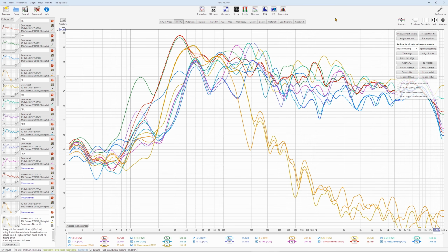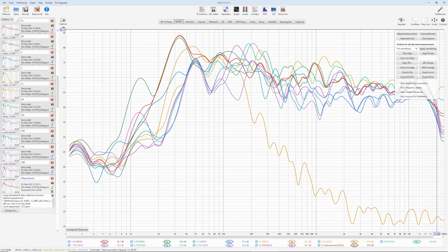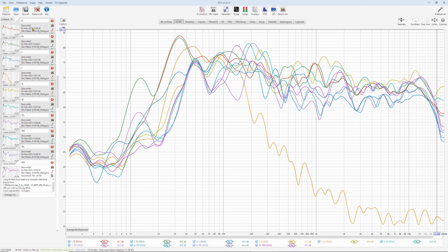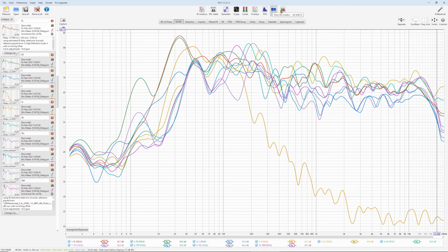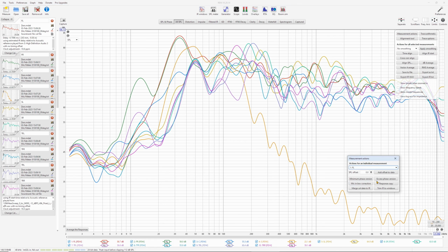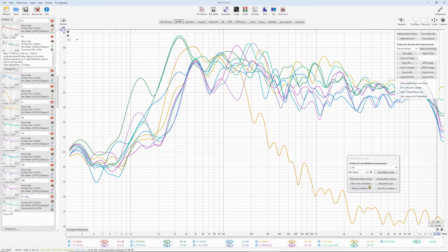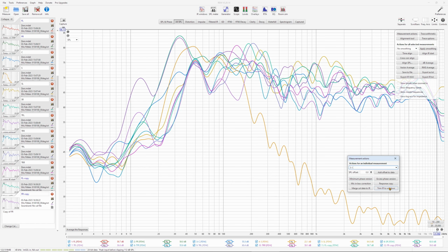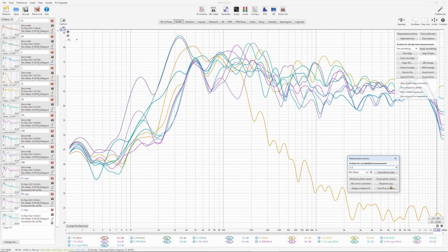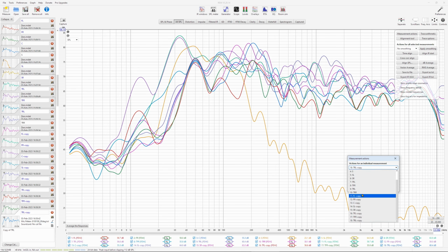Now we have to align the volume levels of all speakers. This is pre-correction volume levels, so that you don't have to correct too much. It doesn't need to be very accurate, but it's good to align them before inverting them. Get rid of all these impulse peak responses. First, create copies of every measurement. FL response copy, FR response copy, C response copy, subwoofer you don't need, SL response copy, and DRR.